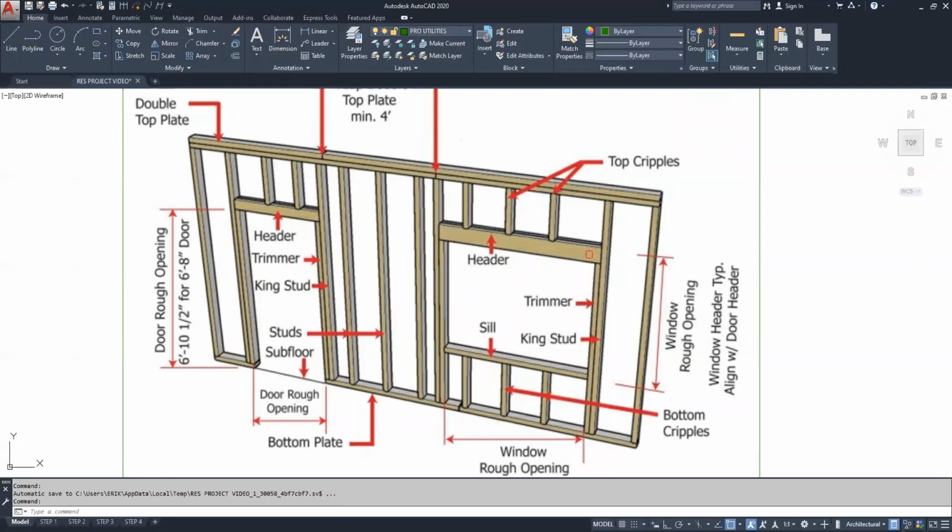What you're looking at here is a typical framed wall. Framed with either 2x4s or 2x6s usually. This is a 2x4 or 2x6, known as a stud, going up and down inside the wall. The spacing between these typically is 16 inches. So we say that's 16 inches on center. So from the center of one to the other will be 16 inches. So even though there's no scale on this, you could say this to this to this is 16 inches. You could see this gap's a little bit tighter.